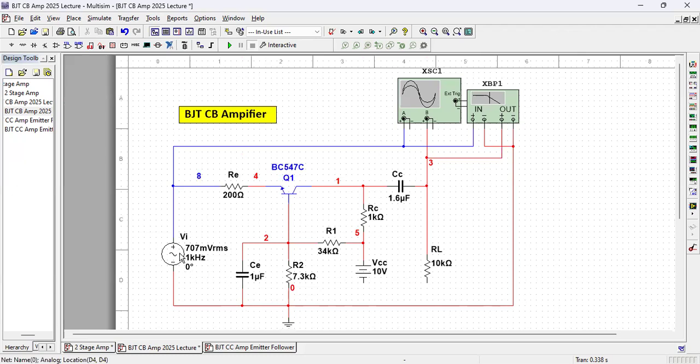And then you have to really, if you are, there are impedance meters normally used in very good laboratories. But maybe in your institute, you may not have an impedance meter, you have multimeters. Multimeters will not measure impedance. If you apply a multimeter here, let's say, at the output, what will happen? Multimeters measure resistance.